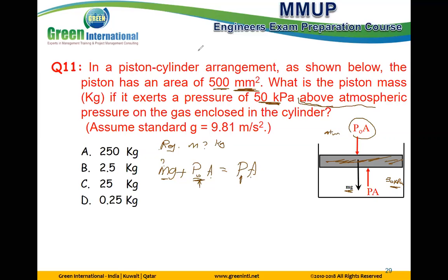Absolute pressure. Absolute? Yeah. This one, again, 50 kilopascal above atmospheric. We talk about here before this absolute, the second datum is atmospheric. He mentioned here 50 kilopascal above atmospheric. It means he measured from atmospheric. So it's gauge. It means this type is gauge.